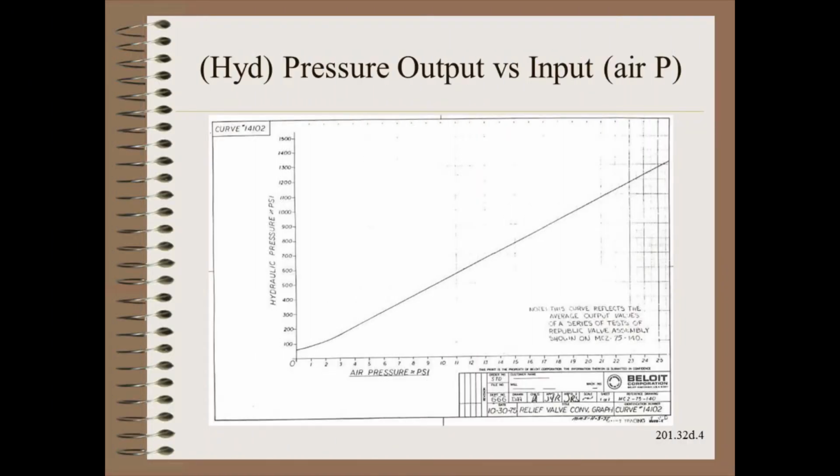Shown here is the ideal performance curve for a precision regulator used on a winder lay-on roller. The service engineer is instructed to test this in the field, on installation, and if there are any questions as to performance. You could do this as a series of plotted data points going up and then going down. Alternatively, you might choose to graph it automatically with a PC-based data acquisition program or data logger.